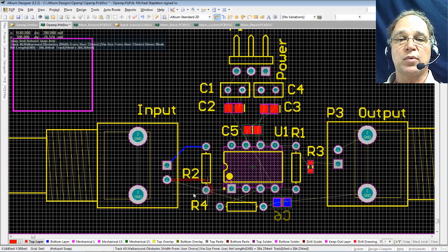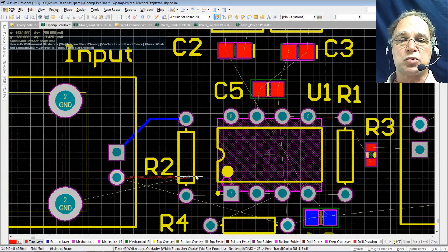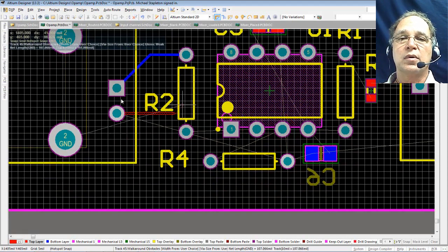Why do we get red? Because I'm routing. See it go around. It's going around. Let's zoom in. It's easier to see. I'm telling it to go straight across. It's going where I tell it as much as it can. And then if I tell it go there and then go down, you'll see where it moves in between those pads trying to route. Right? It can't touch that spot. That's a different net. All the time trying to get here.